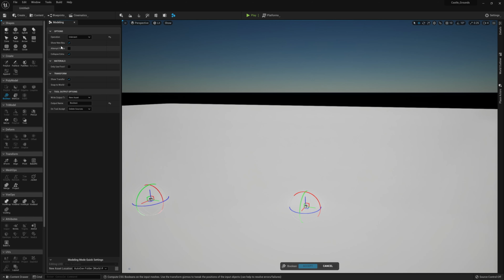There's a lot of different options in here, a couple of quite obvious ones like fix holes is going to try and close any holes that it creates. You can use a new material where the intersection points are, but probably the most important section is down at the bottom where it tells you whether it's going to export a new asset or whether you overwrite the first input or the second input. For my case, I want to create a new asset because I want to keep the original model. If you have it on first, then it will overwrite the model you imported, and then you can choose whether you want the cube that you used to do the intersect to be deleted or to be kept and things like that. This process will take a little while, as I said, so I'm just going to pause the video and come back when it's completed.